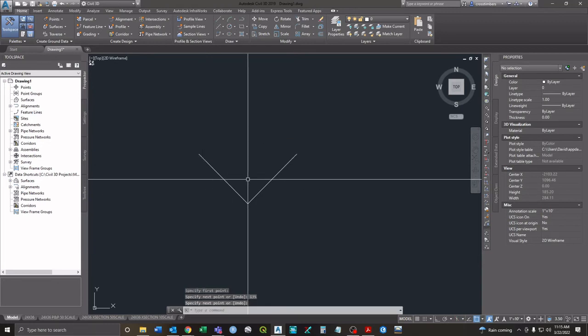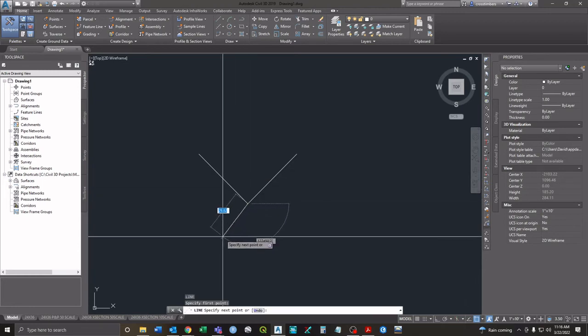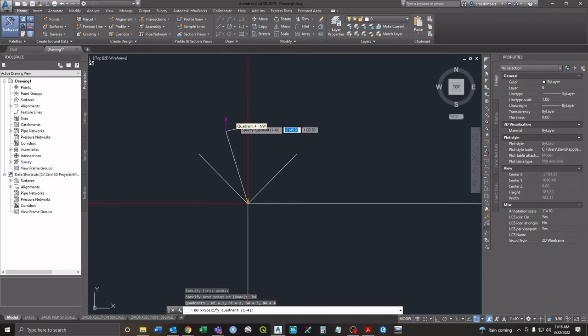or we can actually do it as a bearing. That's where you can say, I want a line. It's the same command. You still specify the first point, but then there's a shortcut subcode to do bearing and distance, and it's apostrophe BD. You have to click your first point first, and then you hit apostrophe BD and hit enter, and now it gives you this whole separate menu.